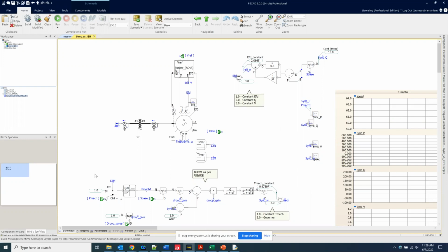So what the excitation system does is you have something which is providing a voltage to the DC field winding of the machine. And that voltage provided to the DC field winding, the rotor rotates inside the machine, you generate an AC sinusoidal wave. Now, what the excitation system is doing is it's trying to change that DC field excitation based upon the terminal voltage of the machine. Now, how many of us think that a synchronous machine is a grid forming device? Why?